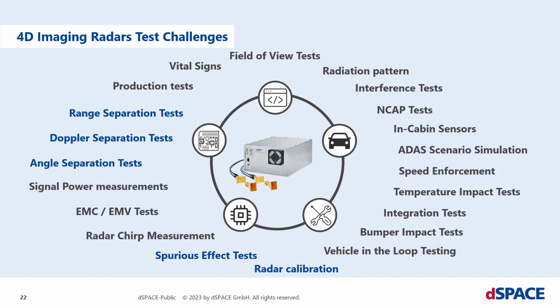To reach the intended accuracy, the radar has to be calibrated properly. The higher sensitivity that is used to detect even the smallest targets, such as a metal can on the road, makes ghost targets more likely. To prevent these ghost targets, even the smallest spurious or artifact of radar processing must be found and assessed.